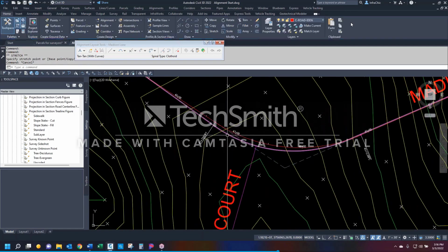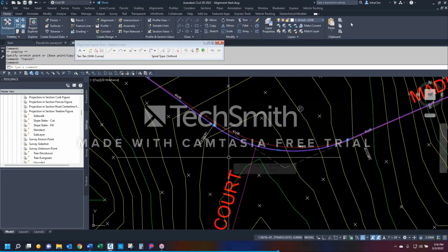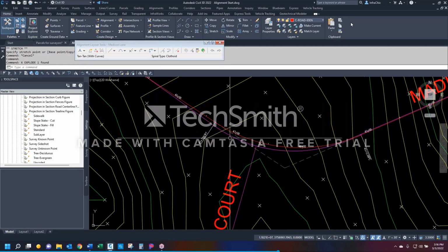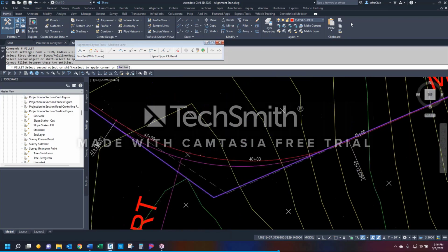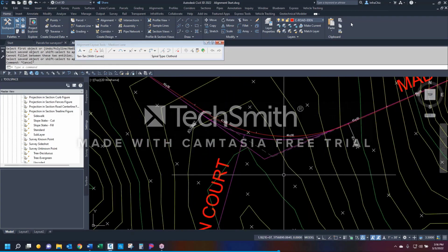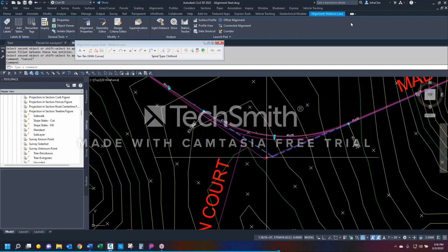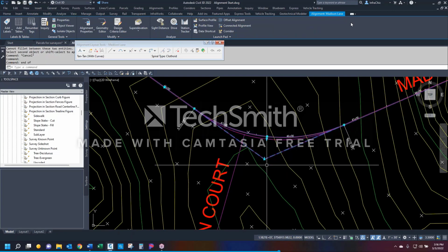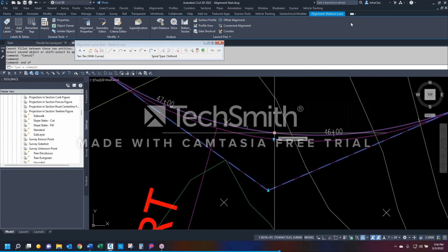It really will. Now, if I really want to know, I would take my polyline that I didn't erase. I would explode it, and then I would fillet it with a 0 radius. I grab here. I grab there. Ah, that's where my PVI should be. That's the cheat method, by the way. Bing. Okay. I got that lined up. Now let's grab it by the alignment.